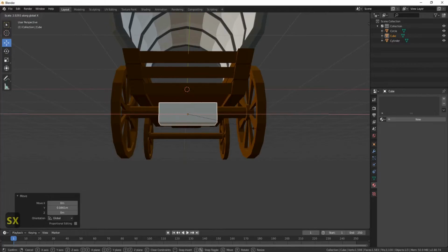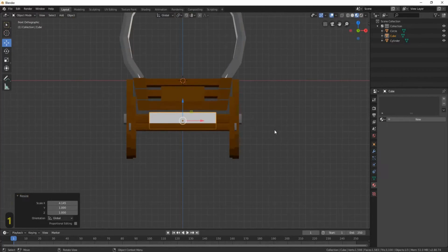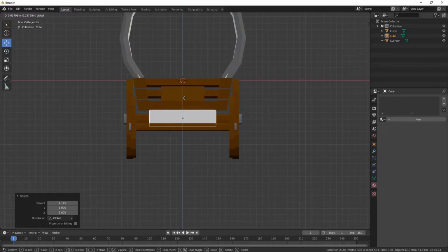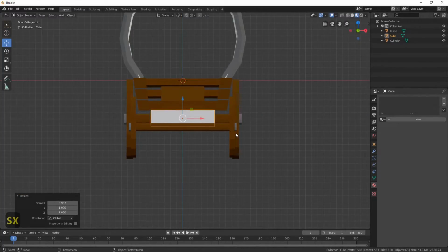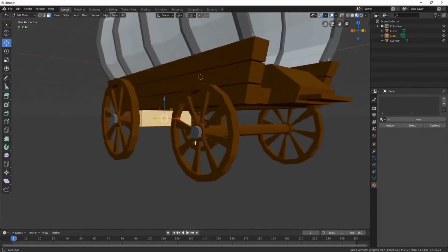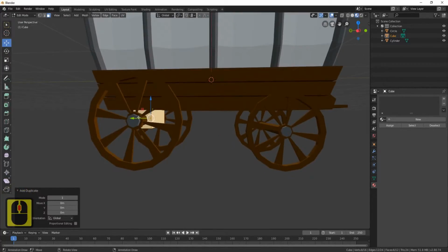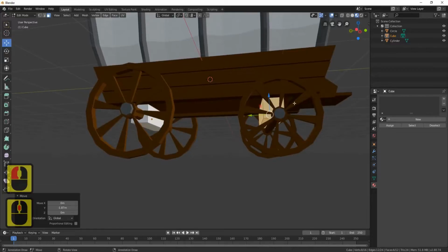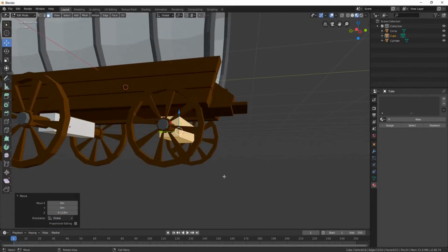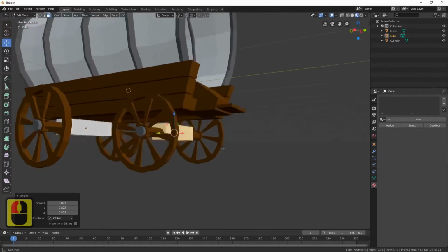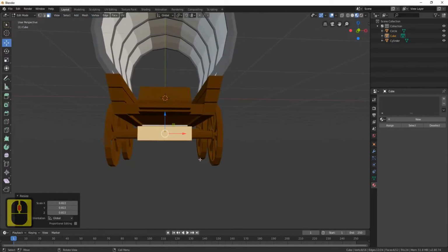And now we need to bring it out so it's round about the edges of here. So now press SX. Let's bring it out. And bring it up just to see, and we'll bring it in just a tad, and now we'll press tab, have everything selected, press Shift D, and let's bring it over now to our front as well, and let's bring it down and make this one slightly smaller and bring it out just a little bit.